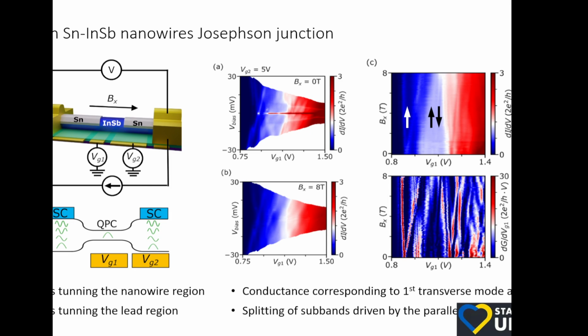Not so many. Okay, so I unfortunately did not put a slide on that, but it's an effect where each of the transverse modes contributes the exact same conductance of 2e²/h per mode. Remember I told you it has a few occupied modes, like 5 or 10. Then each will contribute 2e²/h, and the 2 comes from spin. So each spin resolved mode will be e²/h, and e²/h is a conductance of about 26 kilo ohms. 2e²/h is 13 kilo ohms. 4e²/h will be 6.5 kilo ohms. And so on and so forth.